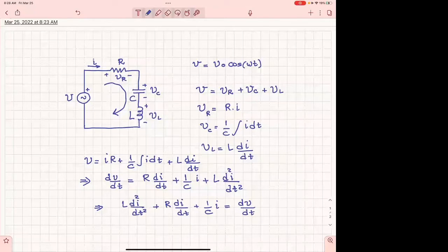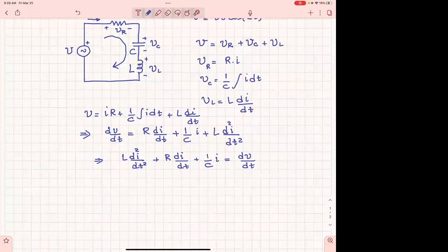You know L, you know R, you know C, you know V. And then therefore you go and solve the second order equation. All right, that's what you have when you have an LC. Well, what if I had 2 C's, C1, C2, and 4 L's? Then I would have a very high order differential equation. Who could solve a higher order differential equation when computers were not available? Even now, why would you have to go to a computer and solve those? The solutions are very complex.